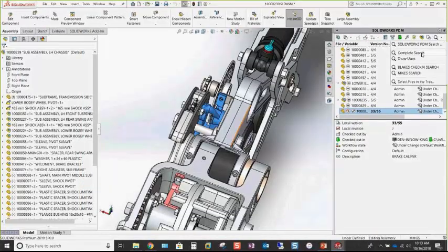Additionally, I can run a search right from the tool. So this is going to allow me to search on a file and open it right from the search tool into my SolidWorks session. Additionally, if I'm using PDM Pro, I can create custom searches if I'm digging into a certain project. So if I have a project that I'm constantly going into, I can create a search that automatically looks into that folder and search into my custom searches. And give it a name like Mike's Search.